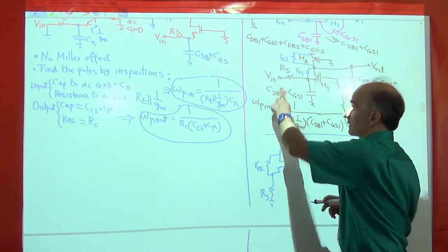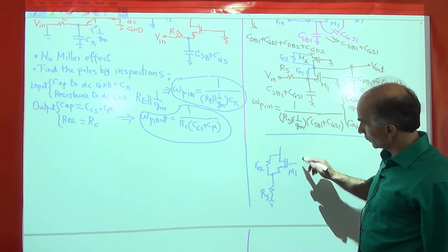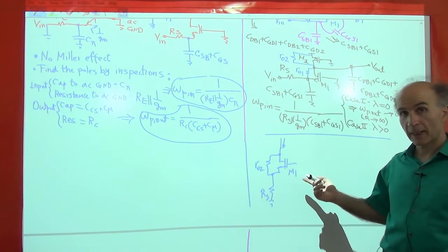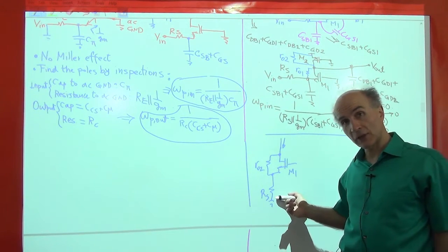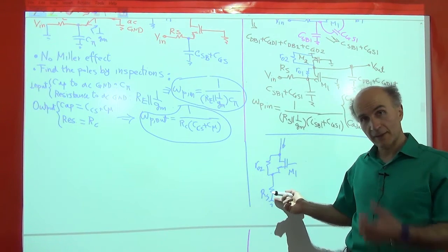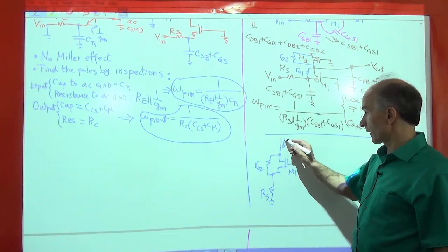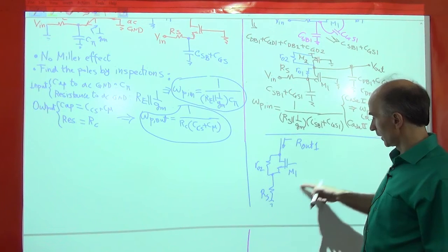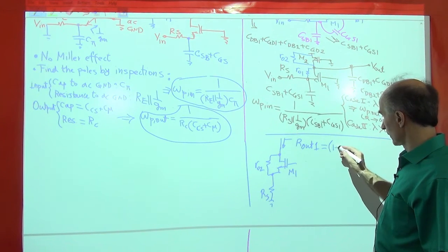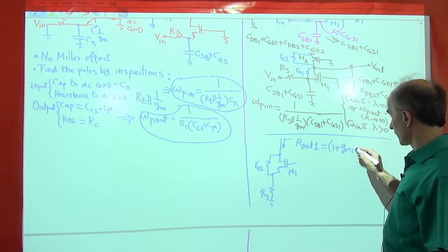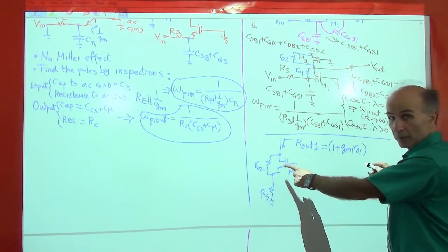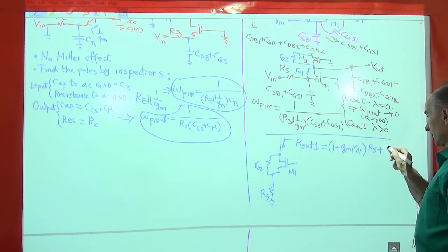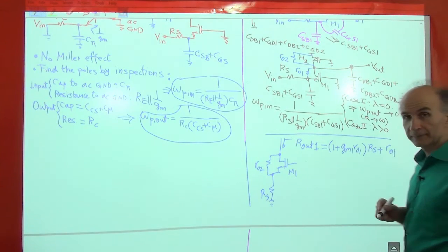So that's why this V is set to 0. Okay, so do I know the resistance looking down here? I do. This is a MOSFET that has source degeneration, and we know the equation for that output resistance from Electronics 1. So if I call this R out 1, meaning R out of M1, then we remember that that's given by 1 over GM1, 1 plus GM1 RO1, the intrinsic gain of the transistor, times the degeneration resistance plus RO1, right? We know that.